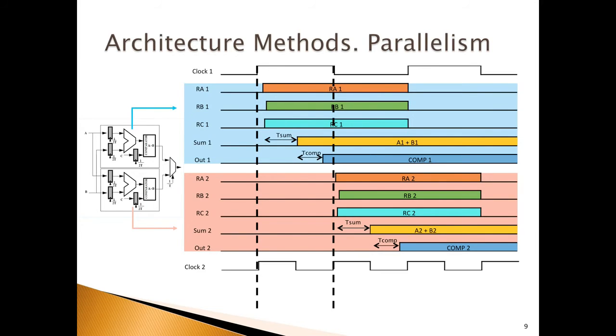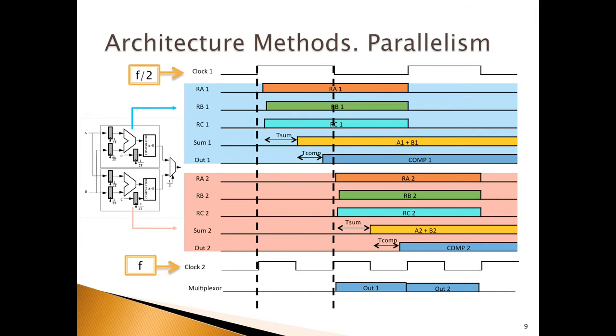By applying the second clock, which has double the frequency of clock 1, we can see that we obtain the output from the first part of the circuit at the rising edge of its clock, and the output of the bottom circuit at the next rising edge. You observe that with this method we obtain double the information and faster. The main drawback of parallelism is the increase of the area needed for the circuit.